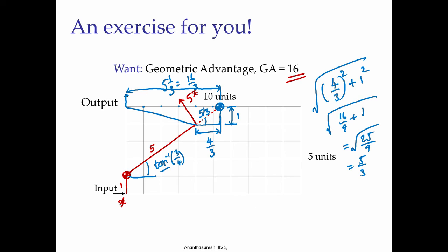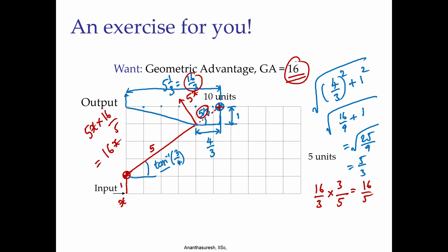In the first stage, we got an amplification of 5x. So, x became 5x, and over here now this one is 5x. So, it will be 5x into this other amplification, this is 16 by 3 that we got, and this is 5 by 3 if I take this instant center. So, that amplification will be 16 by 3 divided by 5 by 3, that will be 16 by 5. So, we get 16 by 5. So, I get 16x, which was our target. This is a graphical method.